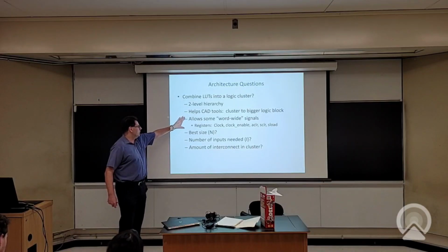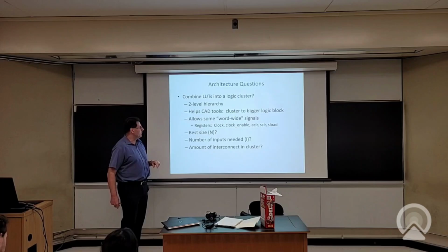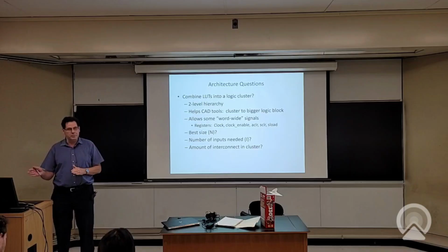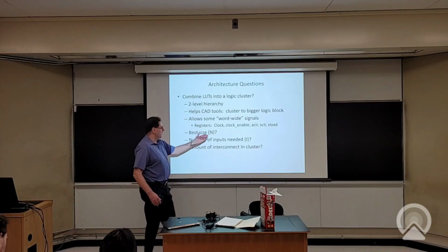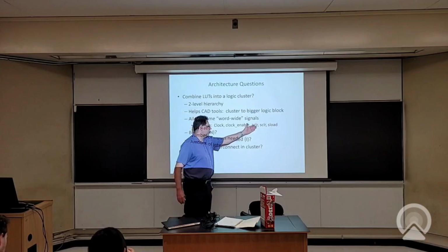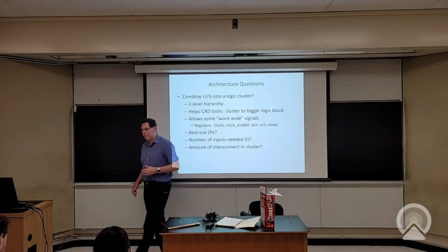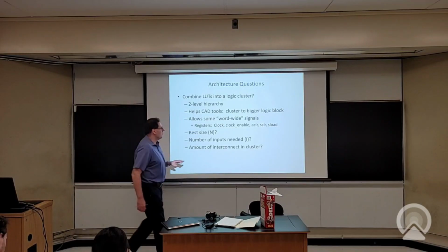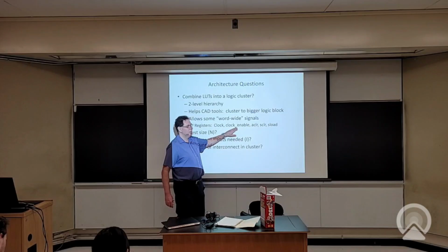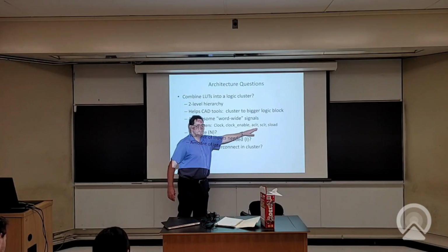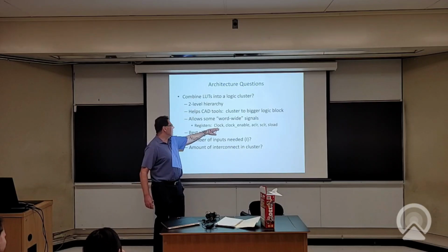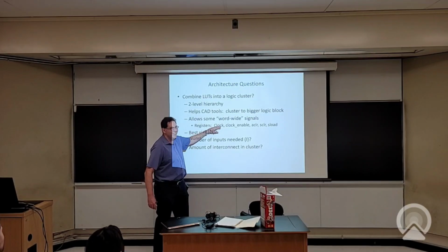We already talked about this on the whiteboard, but it allows some word-wide signals. This is a natural way to say, within this logic block, you all share the same clock. Maybe you all share the same clock enable, the same asynchronous clear, the same synchronous clear, the same S load. Because usually, if you have a design and you use a different clock enable on every single register, a different clear on every single register, and the worst of all, a different clock on every single register, I mean, you are in like lab 2 of 241, and it's not going well, right?